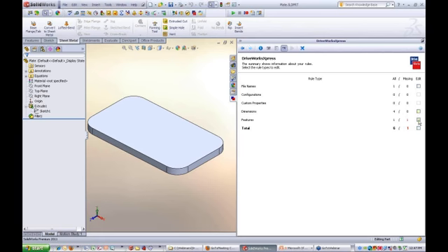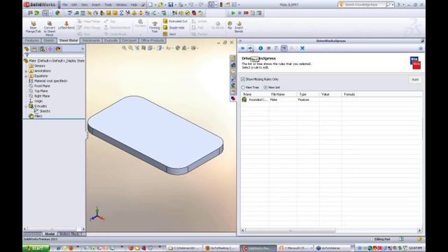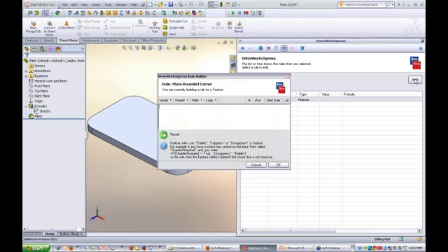I need to, however, control the feature. I've captured it, therefore it needs some sort of control. So I tick the box. Choose next. So what are we doing with this feature? We need to either suppress it or unsuppress it depending on the answer to our tick box. So if I select it and choose build, I can use an if statement. It's under my logic menu here. I can use an if statement.